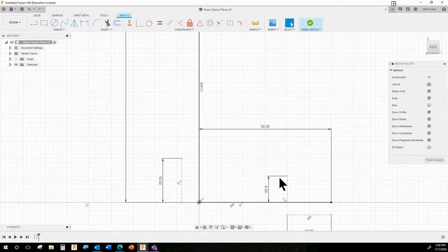Got my reference points for my arc. I know one end of it is going to be here, snapping to this point, and the other end is going to be here, right across from my reference point telling me where 10 millimeters high is. The way this client has given me the information is in 3 points: start point, end point, and some point somewhere along the arc.